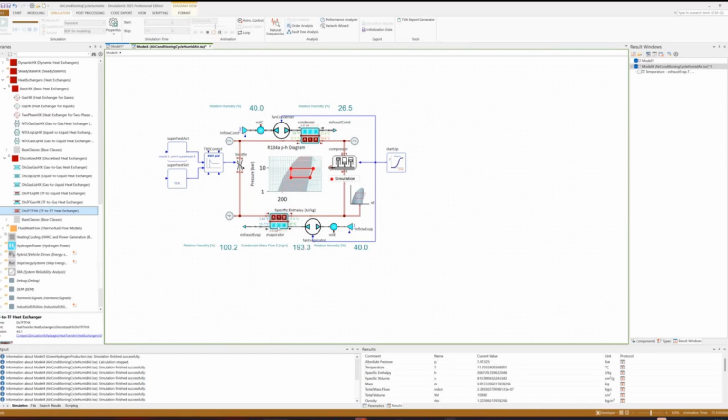If we analyze the mass flow at the outflow, of course, we will see that the mass flow is less than at the input, because we take this condensate water from the system and consider the condensation process. And we hope it will also improve the user experience, so that users can also simulate humidity condensation. In a lot of cases, it totally makes sense to consider the humidity on the gas side.